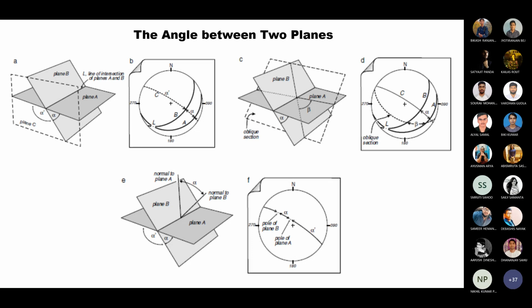So the purpose of this slide or this discussion is determining the dihedral angle between a pair of planes. Here they are marked as plane A and plane B stereographically. So how to do that? You can use the method based on the great circles. What you have to do is plot both planes as great circles, and then label A and B as labeled in the picture.